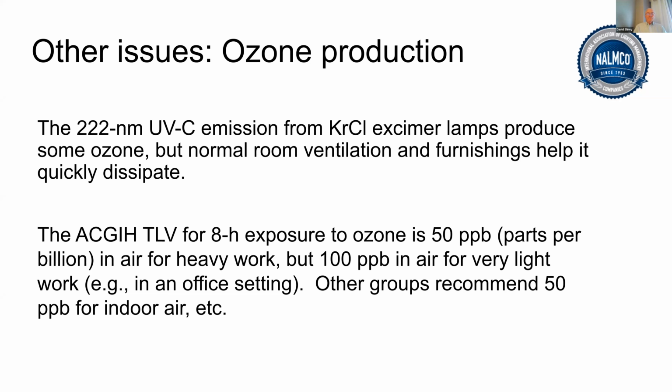The normal room ventilation and also furnishings quickly dissipate the ozone. And the ACGIH TLV for an 8-hour exposure to ozone is 50 parts per billion, 50 ppb in air for heavy work, but 100 parts per billion in air for very light work, for example, in an office.